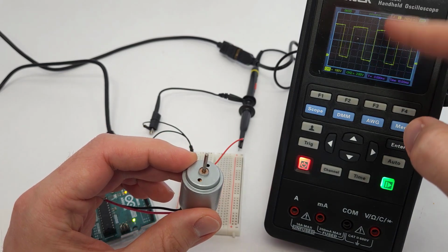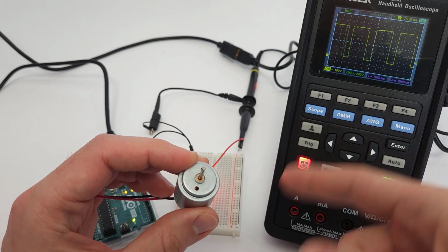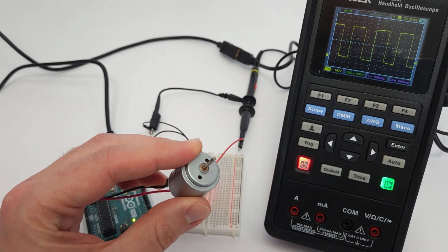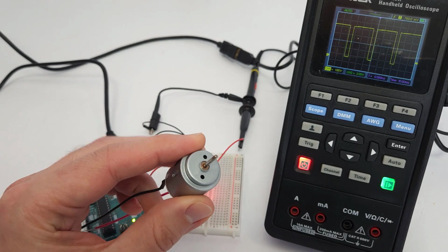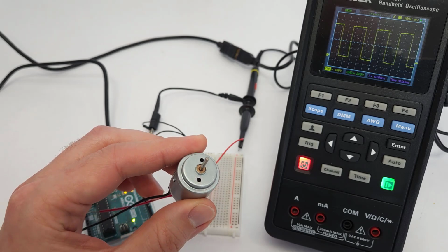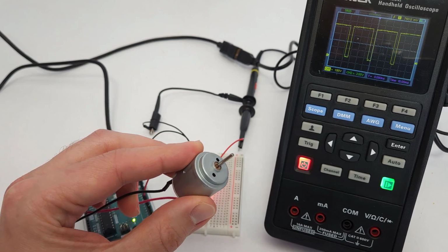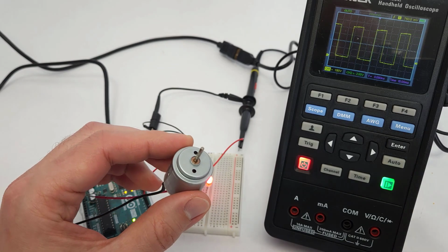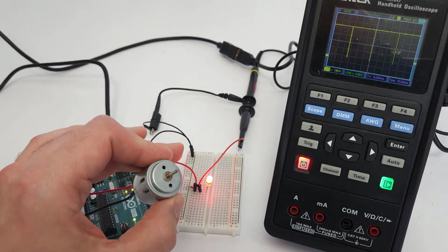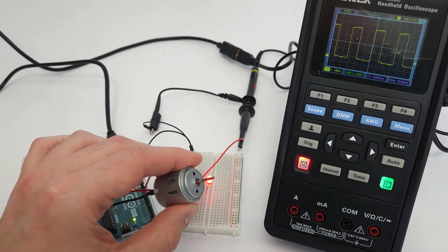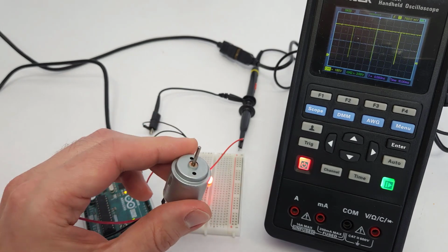So if this frequency is oscillating too quickly, turning on and off, then the motor never really gets to build up any speed. Motor dynamics and time constants and all of that are a totally separate topic for a whole series of videos that we could go into. I do have an intro circuit theory playlist that you could check out if you want to learn about time constants. But point being, there isn't a single correct value for that prescaler. It's going to depend on the physical system you're driving, whether it's an LED, a motor, or something else that you are using a PWM signal to control.